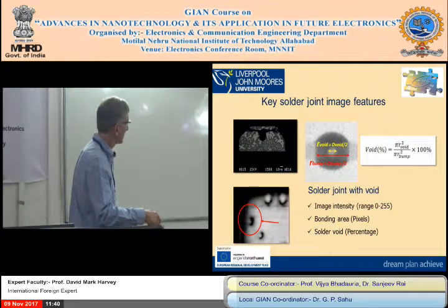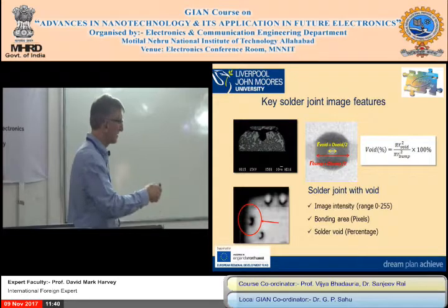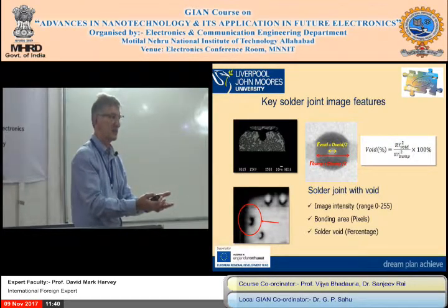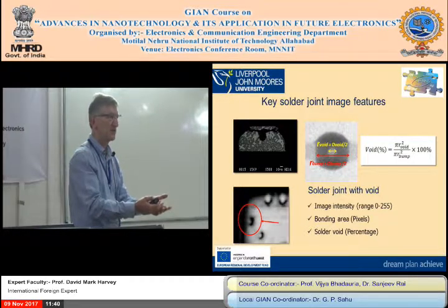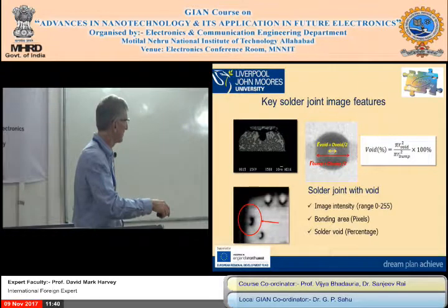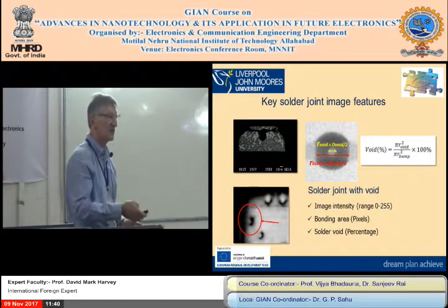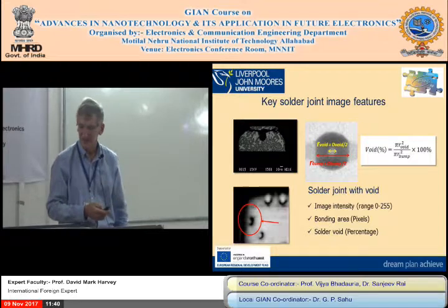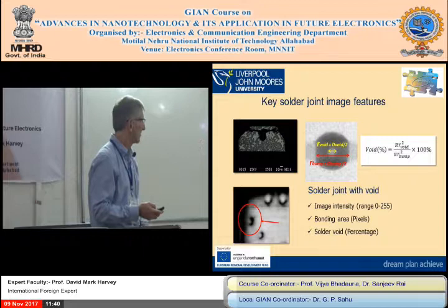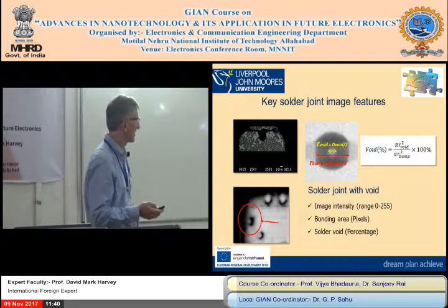We'll go into this in a bit more detail, because when we do the scanning, that joint is broken, but because you've got this shape in the middle, it doesn't reflect the ultrasound as much. So this joint actually looks like a good joint. You can see that it's broken, and the reason is this bit disperses all the ultrasound. So we found a way to solve it. This is just working out the voids compared to the diameter of the joint. Anyway, we'll go back to that.